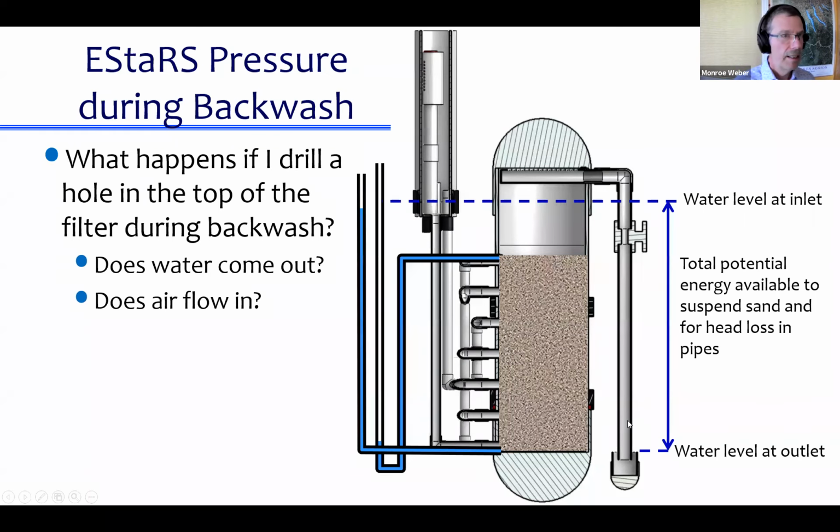well, look, the water is exiting into this little bucket at the bottom here. That free surface represents atmospheric pressure. And as we go up, the pressure has to drop, right? As you're going up in a swimming pool, the pressure drops. So as we go up, the pressure has to drop. And that means that the pressure inside the top of the filter is way below atmospheric pressure. Okay, cool insight.